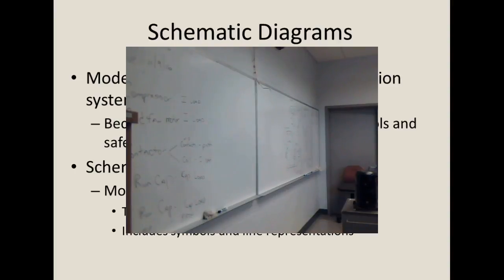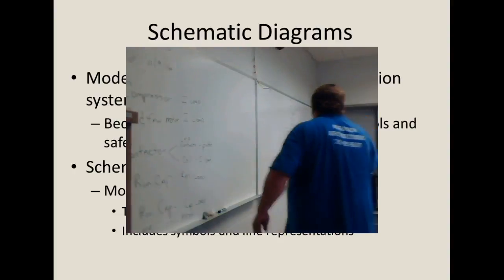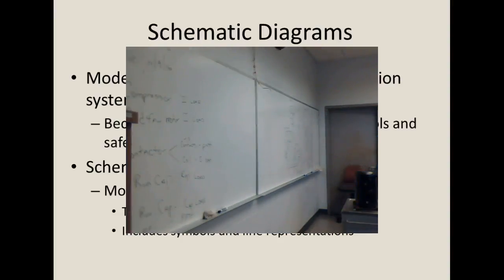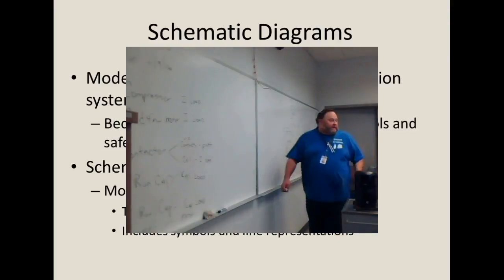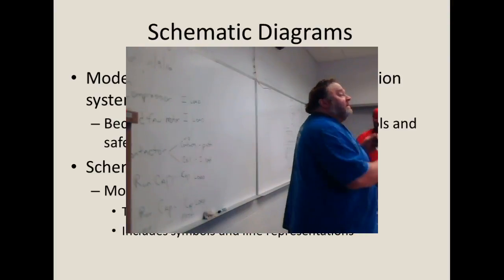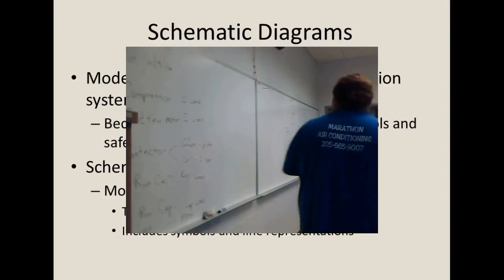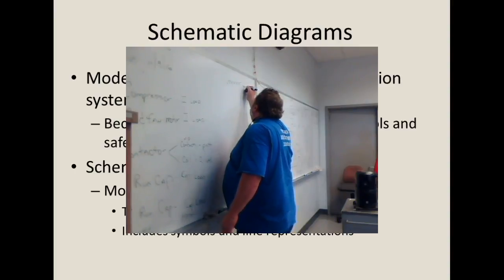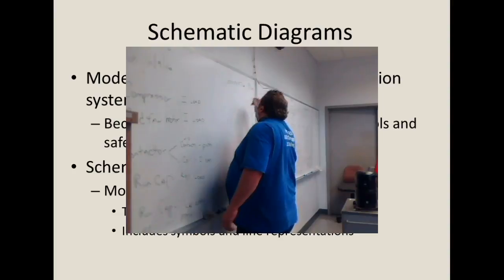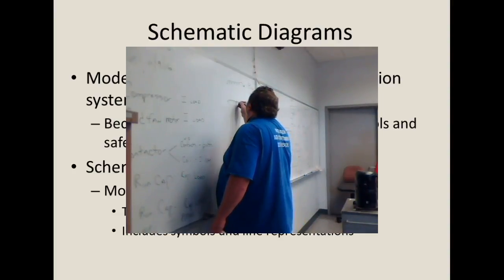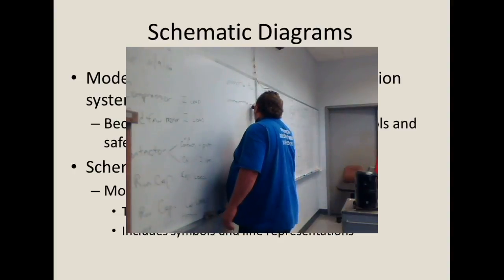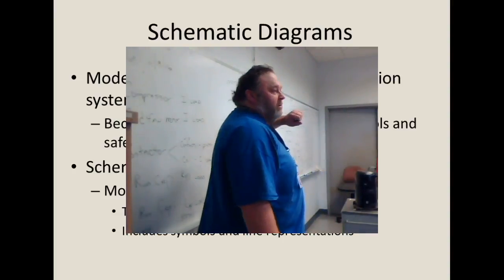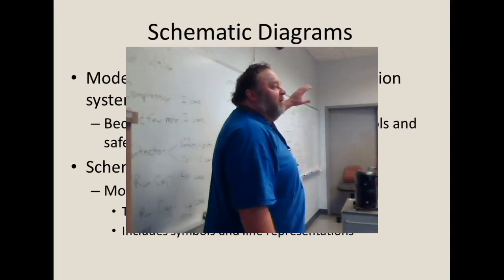Now inside this compressor, there is a motor. But just like inside this condenser fan, it's the same type of motor. It's a PSC motor. And inside it, we got two windings, we said, right? We have a winding we call run. We have a winding we call start. We said the run winding was thicker and shorter. The start winding is longer and thinner.